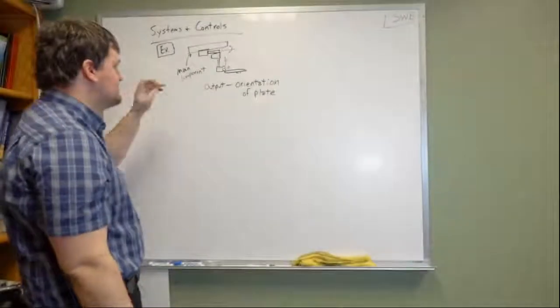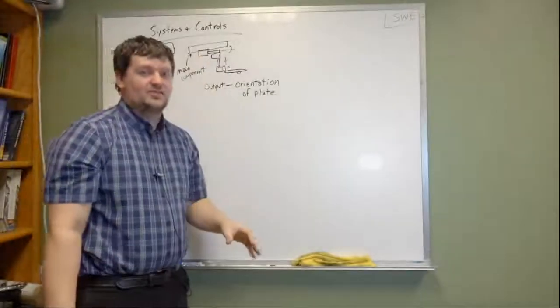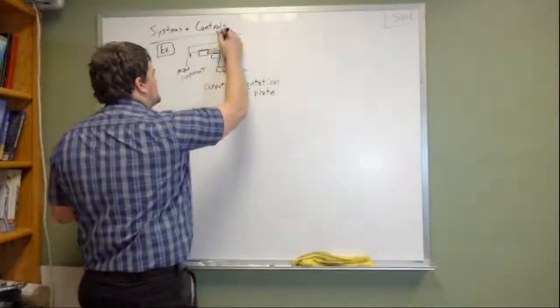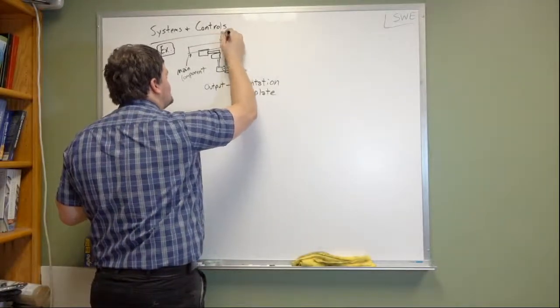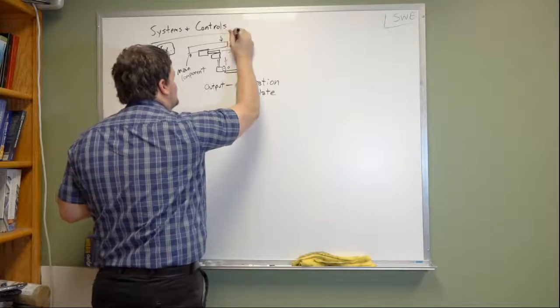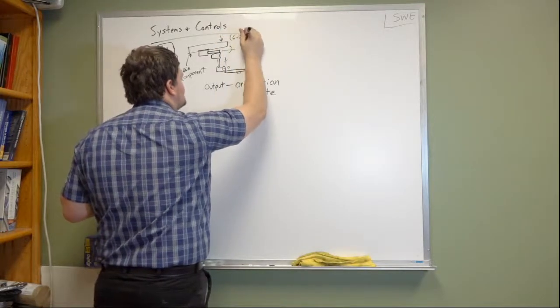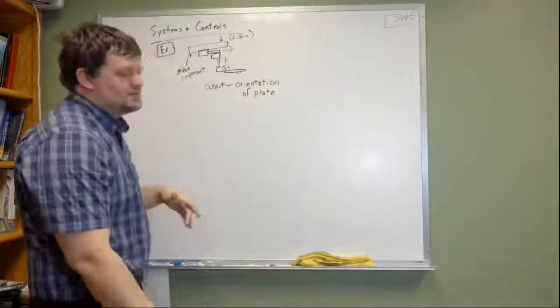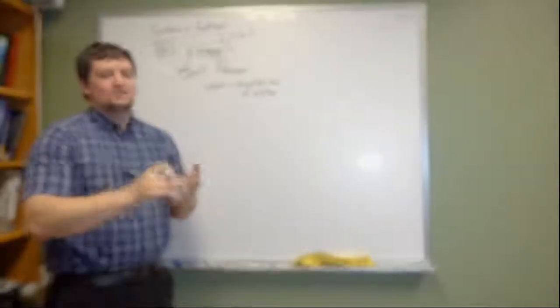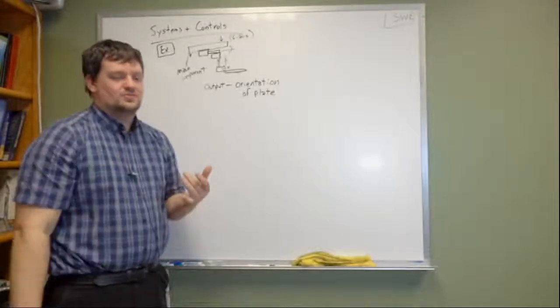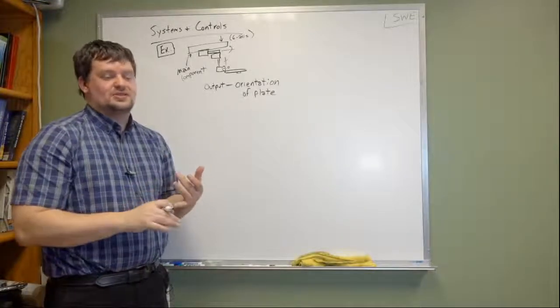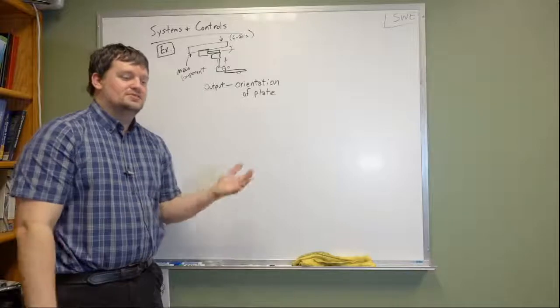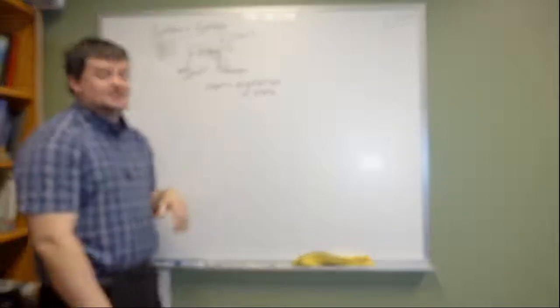If we have this main component, the gimbal is hanging off of it, but this main component is going to be experiencing forces. We've got our 6-axis forces that this is going to be facing. And we're going to be experiencing accelerations in the XYZ directions, angular accelerations about the XYZ axes. So that's your 6 axes again.